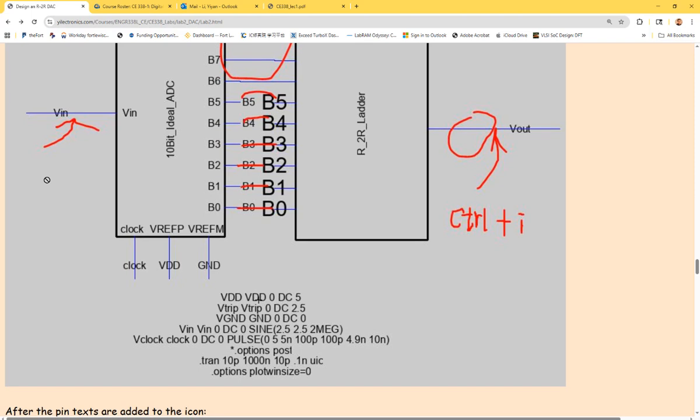And you see in your SPICE code, when you are trying to use a node, for example, VDD, and you have a node here to 0, that node is actually the name of the arc, and the way to change that is Control I. So you left click, single click on the arc, and you press Control and I, and it's gonna pop up the window and let you change the name of it. After you change the name, it shows the name on the top of the wire or arc. So if you see that, that's a success. It's the same here. You can see that it's directly on the top of it. It's not at the bottom, not on the side, it's directly on the top of it.